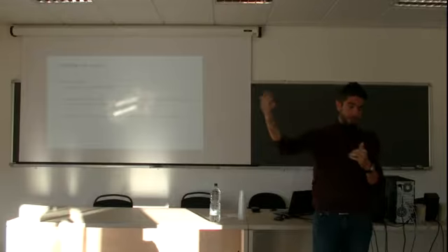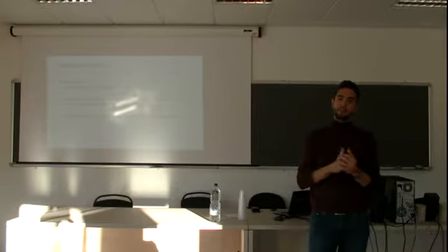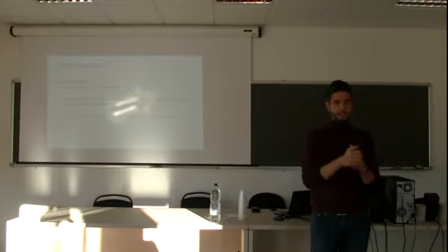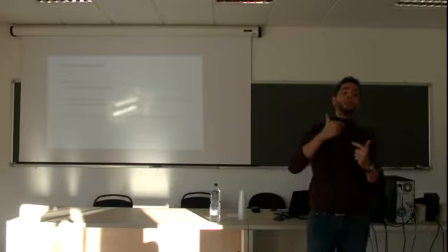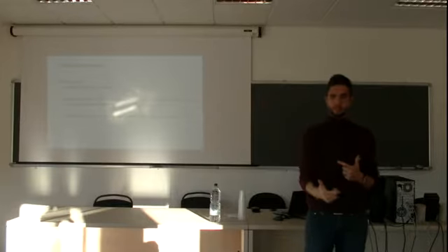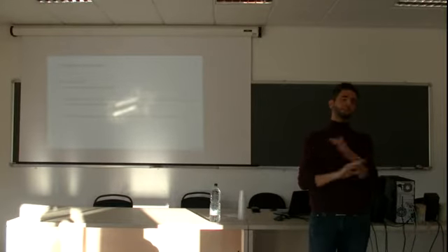If the problem that I am simulating is in narrow cavities, or there is something blocking or limiting the movement of PCM, I assume PCM doesn't move, because it costs me 20-30 times more computational effort to add this physics, natural convection. In the literature there are plenty of papers on that. What if I increase the thermal conductivity based on Rayleigh number, and I don't need to apply motion, I don't need to apply Navier-Stokes equation? That will save me a lot of time.